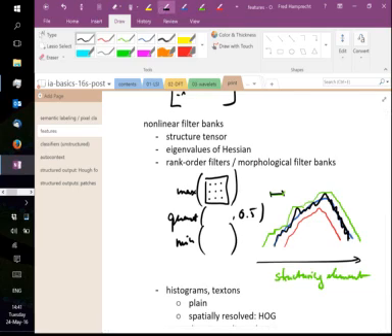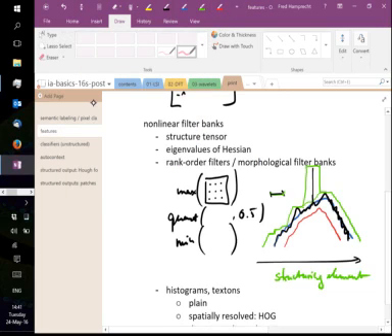And now the interesting thing is, if my data has outliers, so if there's a spike in my original black curve, then of course the maximum filter will pick up this spike. The minimum filter, the red signal, will not see it at all. But the median, the blue one, will also be robust to that outlier. So if I had used a Gaussian smoothing, let me find a different color, a Gaussian smoothing would have been sensitive to this outlier. So compare the pink curve with the blue curve. The Gaussian is sensitive to outliers, but the median is not sensitive to outliers.